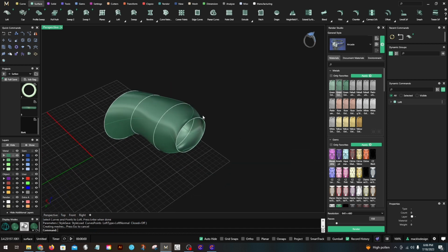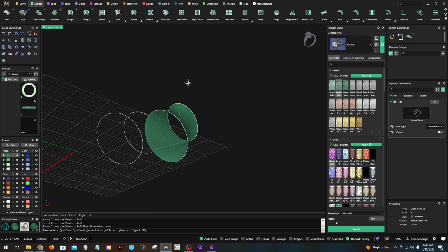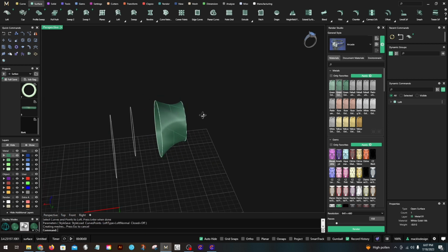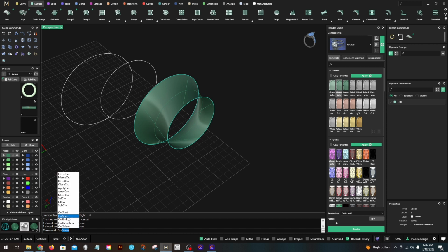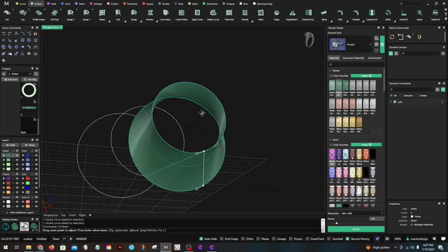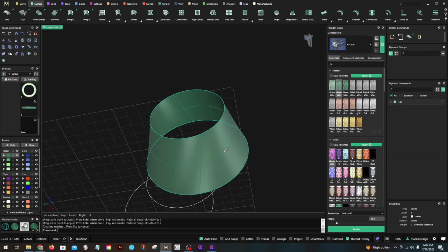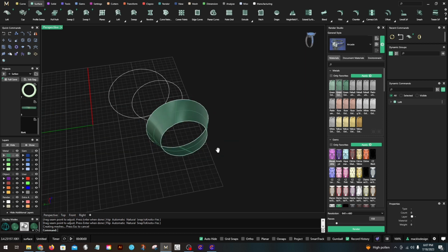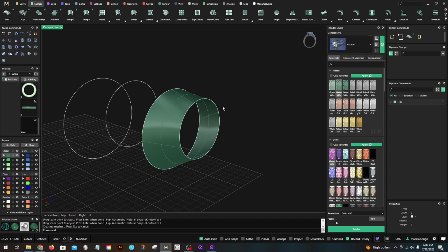All right, so you can see lofting just takes you from one curve to another. I use it often if I don't want to bother putting a line here. I can just go and loft straight to that. Now you'll see there's a twist there, and it's because of my curve seam. So if you type in curve seam, there you go. Let's try this and see what happens. There you go. See how it straightened it out just a little bit? So most of the time that twist won't really bother you unless it's very extreme. And if you want to change it, that's how you do it.